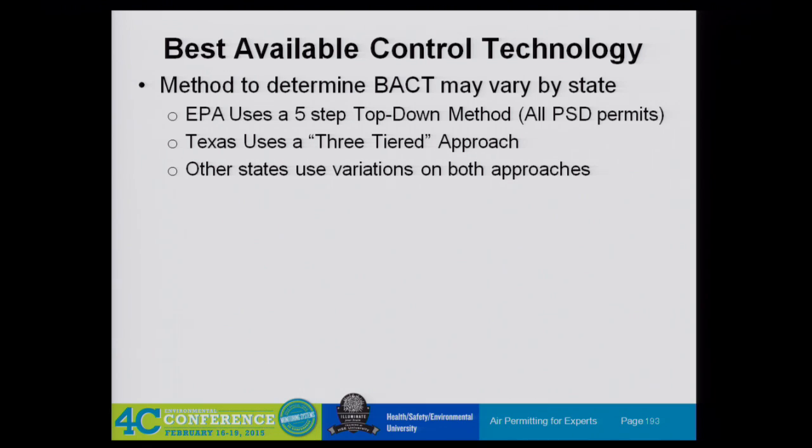Agreed. As more people adopt it, more people are forced to adopt it. Right. And as new technology is created and is proven, so it will naturally get tougher and tougher, whether that's the intention of the company that's adopting it or not. Yeah. It is the intention of the rule. Right. We saw that with boilers for a long time, where the BACT was way down here and the old NSPS rule was way up here, and they didn't match anymore. So the NSPS almost became meaningless because anybody that put a new boiler in had to do BACT, and that was a much lower level than what the RACT rule probably was for the state.